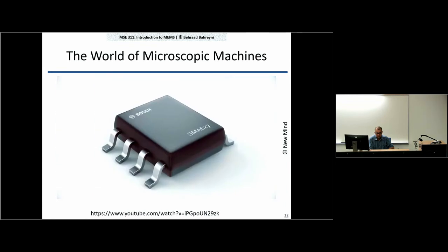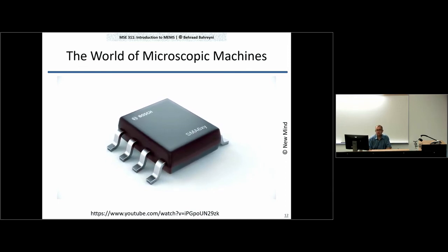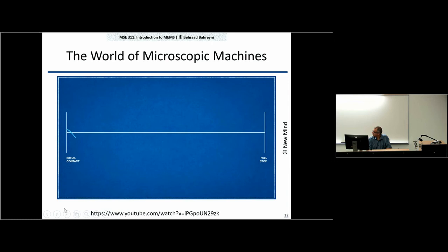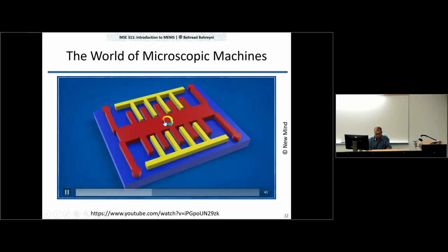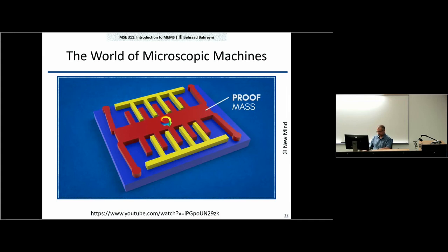The accelerometers used in automotive airbag sensors were one of the first commercial devices using MEMS technology. They measure the rapid deceleration of a vehicle upon hitting an object by sensing a change in voltage. Based on the rate of this voltage change, the on-die circuitry subsequently sends a signal to trigger the airbag's explosive charge. The accelerometer mechanism is composed of a capacitive finger structure consisting of a pendulum assembly that forms the proof mass. This compliant structure deflects under acceleration or deceleration.